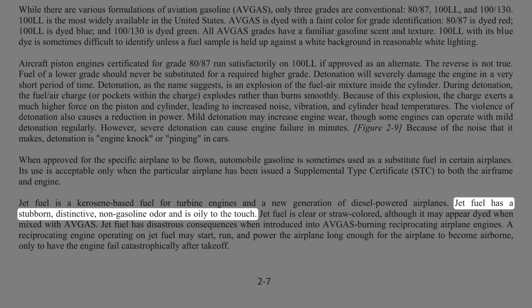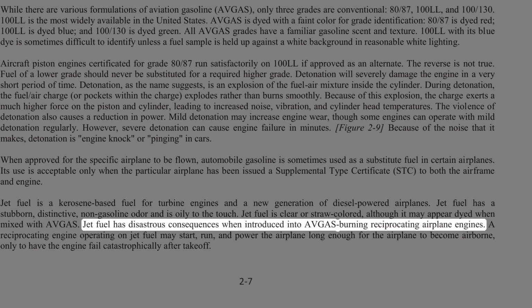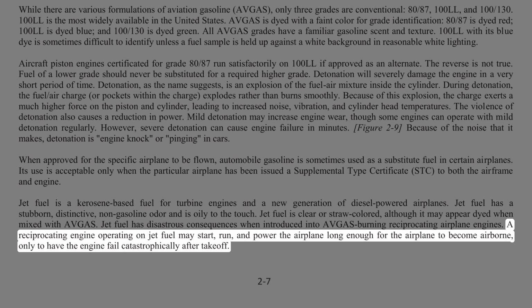Jet fuel has a stubborn, distinctive, non-gasoline odor and is oily to the touch. Jet fuel is clear or straw-colored, although it may appear dyed when mixed with avgas. Jet fuel has disastrous consequences when introduced into avgas-burning reciprocating airplane engines. A reciprocating engine operating on jet fuel may start, run, and power the airplane long enough for the airplane to become airborne, only to have the engine fail catastrophically after takeoff.